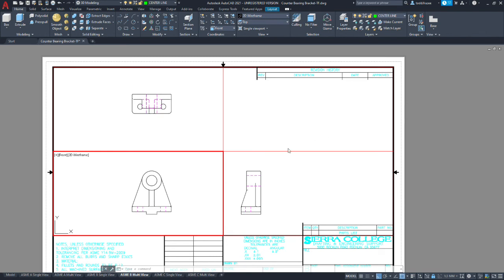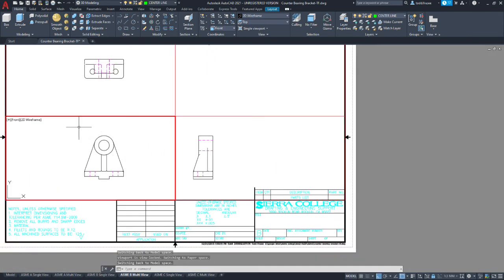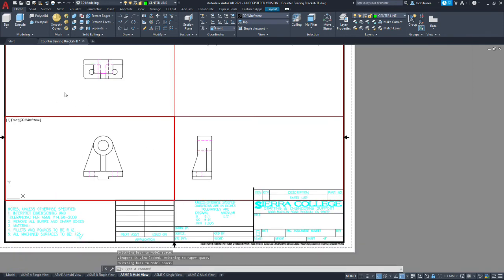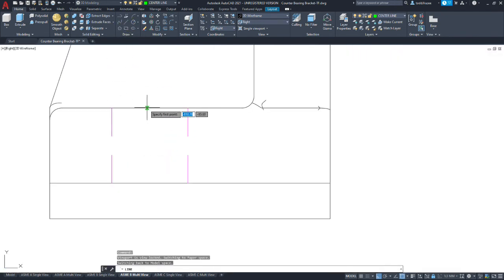Now there's a center line command that allows you to generate an automatic center line between 2 other lines. One flaw with it is we need to use the lengthen command, and it won't allow you to have the center line go beyond. So we're going to manually draw these, but if we're in the correct layer, it should default to a line type that's a center line.